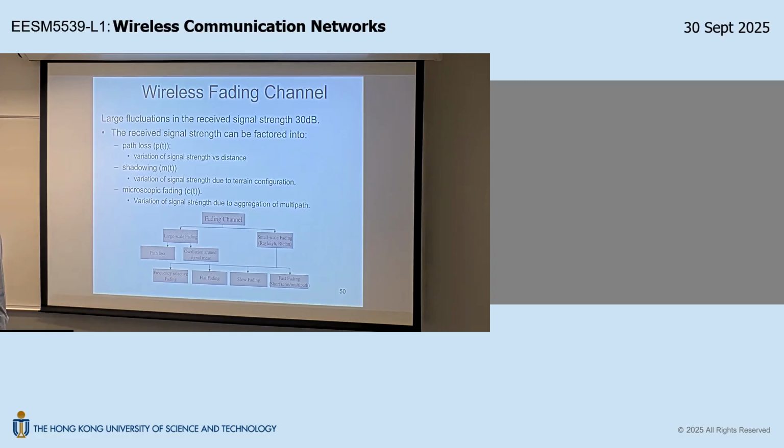If the output is alpha 1 y1(t) plus alpha 2 y2(t), for all alpha 1, alpha 2, and for all x1, x2, then this is called the superposition principle, and this is called a linear system. So linearity, always think about superposition holding. Superposition means if you input a weighted combination of the signals, the output will also be the corresponding weighted combination of the outputs.